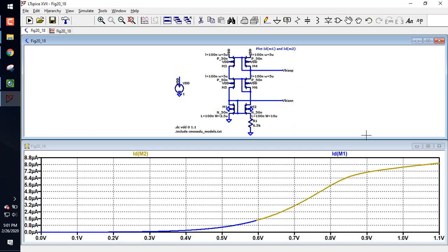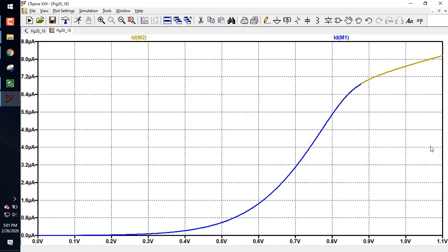So I hit run, and I see that, hey, it's matching better, but it's still not perfect. The output resistance is still bad. Everybody see that? So everybody sees the currents are matching better. Everybody got that? They still have a large dependence on the VDD. And more importantly, I can't go to as low a voltage. I'm only going now to like 0.85 volts, whereas before I was going to like 0.45. Does everybody see the problem?